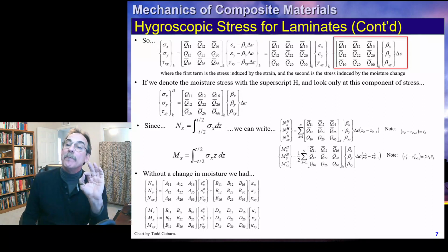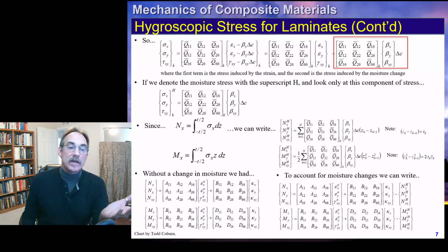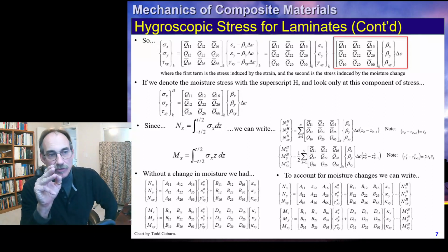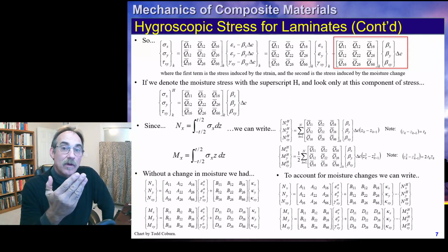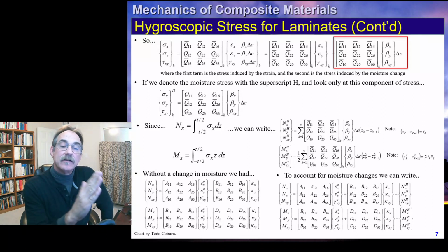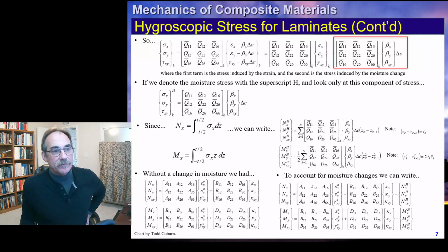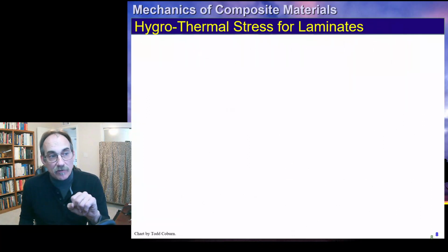And if we start measuring the actual strains, take this total strain and curvature that we find on an element, and if we want to calculate how much of that causes stress, we would have to remove the fictitious virtual running loads and moments due to moisture or hygroscopic effects from the running loads of the element. Okay? So we have seen this approach for thermal loads, and now we've seen how this works for moisture effects.